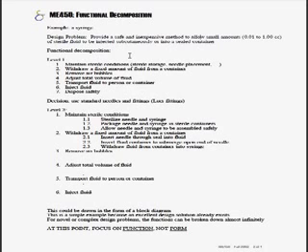Level 1 of the functional decomposition is the high-level requirements. It needs to remain sterile. You want to withdraw a fixed amount of fluid. You can't have air bubbles. You want to be able to adjust that total volume of fluid. You want it to be transportable to a person or to a container. That needs to be injected and disposed of safely. Maybe you want to use standard needles and fittings, for instance, luer fittings. This is level 1. Level 2 is moving in at a finer level of decomposition.